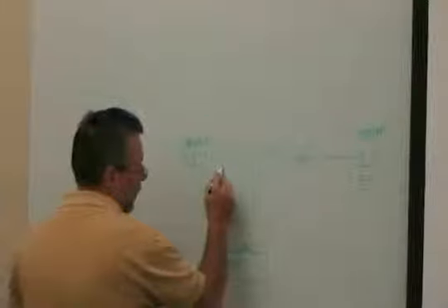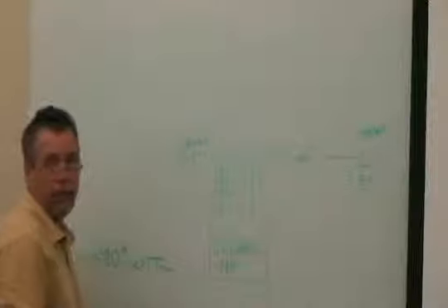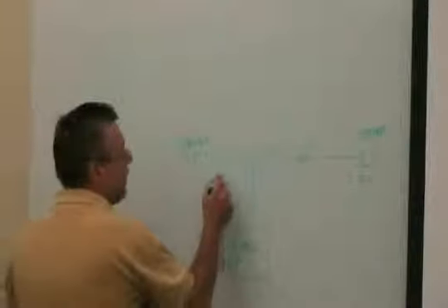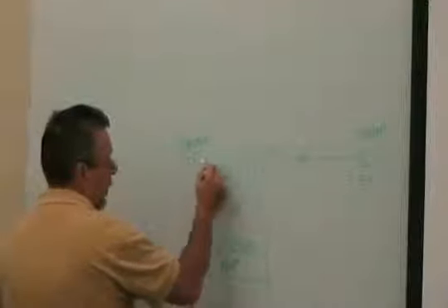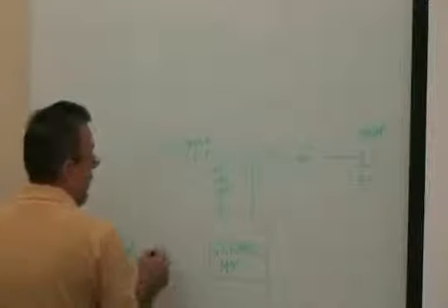What I may have to do with some types of boiler is have a little bypass right there. It takes some of the hot water and mixes it with this water, heating the return back up to prevent the boiler from condensing. This might be just a small sidearm flow right there, but most of the water is going to go here and mix 140 with 59. Make 70-degree water, which is maybe what I want to maintain as a minimum supply water. So that's how the boiler system works in most cases.